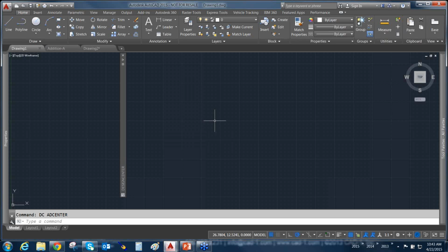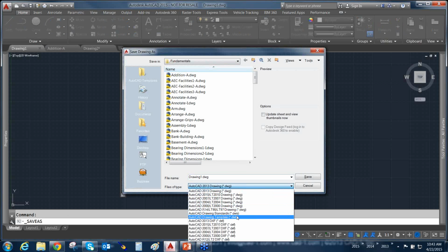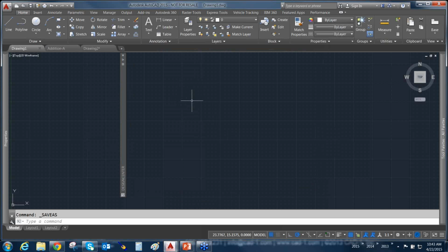And when I'm done working with it, when I'm done cleaning up this template, that's when I hit Save As. That's when I choose a template. And that's when I give it my company name and all of that, and I put it up on the server. It's not a good idea to just hit Open and open the template and just start working in there. Now, for those of you who are going to be managing the template, yeah, go ahead. After you've created the template and I've got just that template file up on my server, I need to tweak a layer, hit Open, pick your template, and work it. But don't let everybody try to open up the template. It's just bad news. It's a standards file. You want to keep it safe and secure.